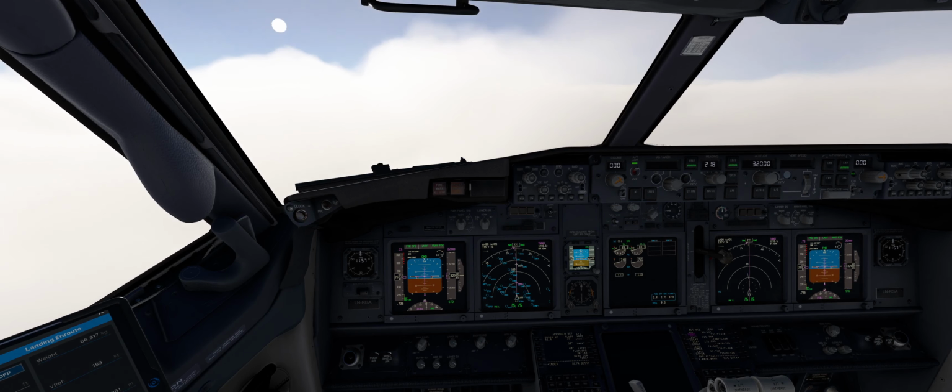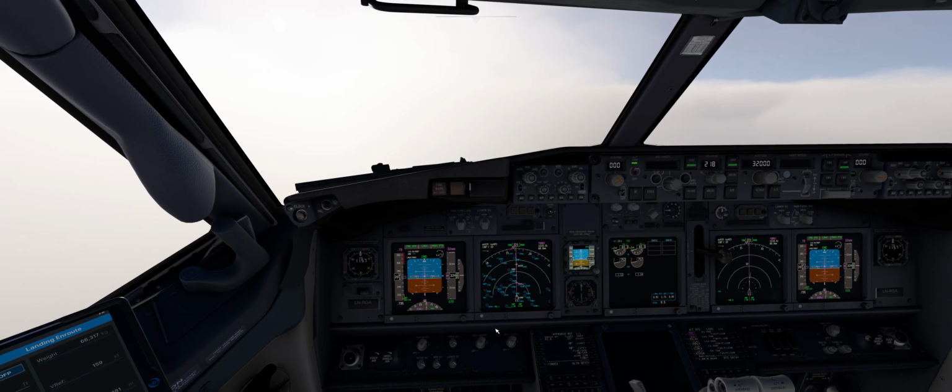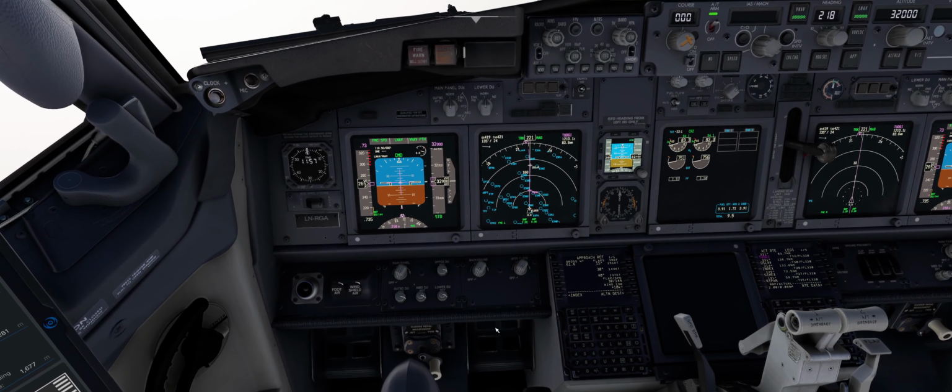So if you are planning to land at the short runway which is contaminated, and we have strong gusty conditions as well, but these gusty conditions, remember, should be within your limitations, and limitations on contaminated runway, for example for crosswind component, it's much more lower than for dry runway. It's no longer what you can see on the flight crew operation manual FCOM. You have to pick up it from your operation manual part B.